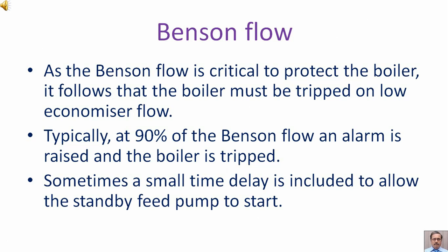As the Benson flow is critical to protect the boiler, it follows that the boiler must be tripped on low economizer flow. Typically at 90% of the Benson flow, an alarm is raised and the boiler is tripped. Sometimes a small time delay is included to allow the standby feed pump to start.